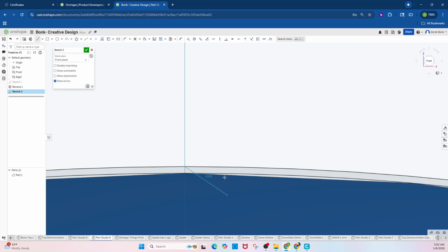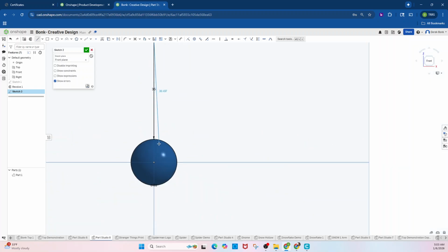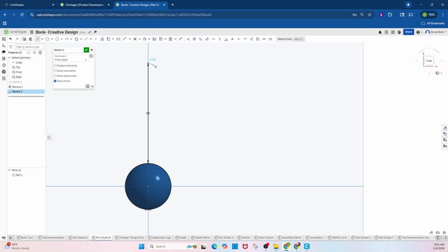like that. And then you're just going to go up 35 millimeters. So what you do is you hover here, click, when you see the white box there, type 35, enter, zoom back out. There you go. And then you're going to come over 5 millimeters.